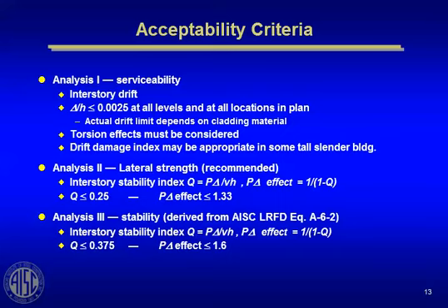there is some data out there that says, okay, if you rack a story this much with a drywall partition, it takes this much drift to cause the first cracking of that partition. And there's some data out there that suggests the same thing for masonry, clay tile masonry.